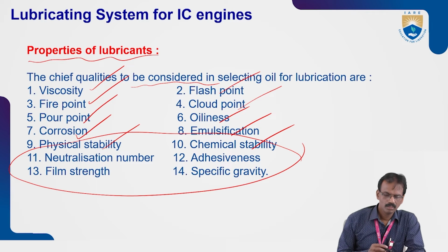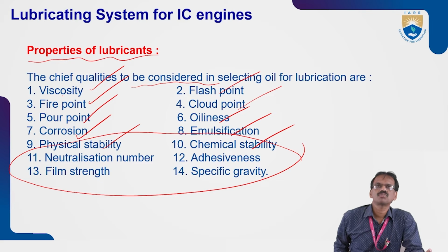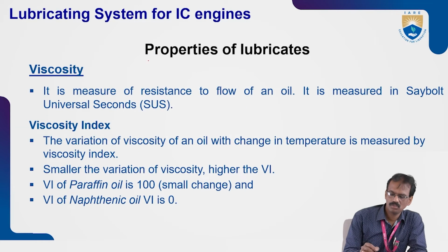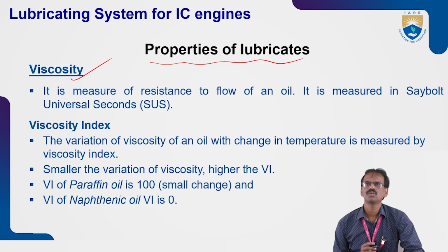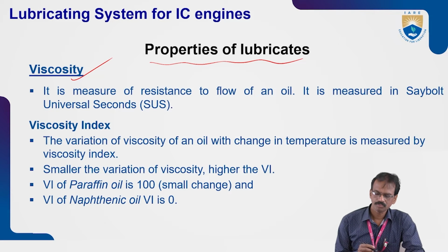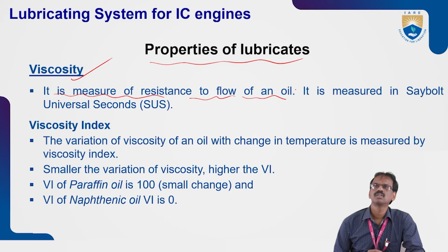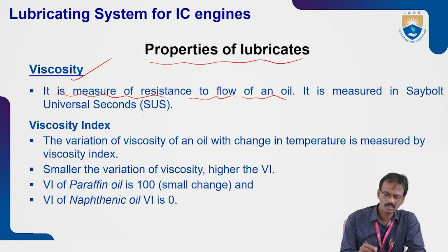We'll see first what is viscosity, and what is the importance of viscosity for the lubricating oil. The first property of lubricant is viscosity. It is the measure of resistance to flow of an oil. It is measured in Saybolt Universal Seconds, SUS.